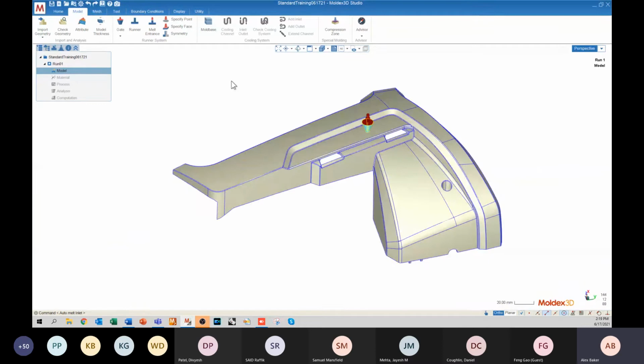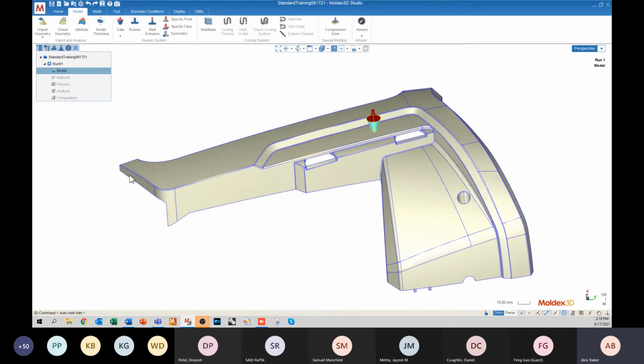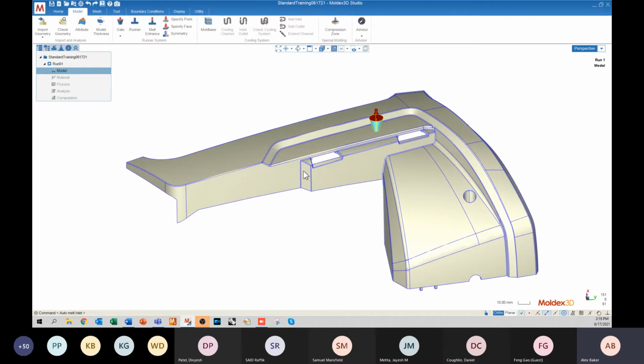So we are going to be assigning what we call a mold temperature. So it's going to be assuming that the temperature on the surface of our geometry is at a constant temperature, and that's not realistic. The reason for that is because heat is always going to propagate through your mold, and there's always going to be a distribution of temperature through your mold as the heat is transferred from your part geometry out to your cooling system.